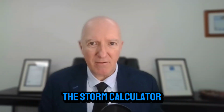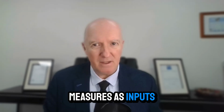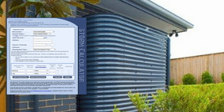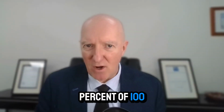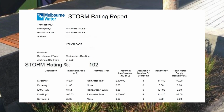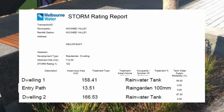The STORM calculator requires impervious surface areas and associated treatment measures as inputs that, when combined, provide a STORM rating percent as an output. A summary of the inputs and results is printed as a STORM rating report. To meet the standard, a minimum STORM rating percent of 100 needs to be achieved. In this example, a STORM rating percent of 102 has been achieved by providing a rainwater tank for each dwelling and installing a rainwater garden.